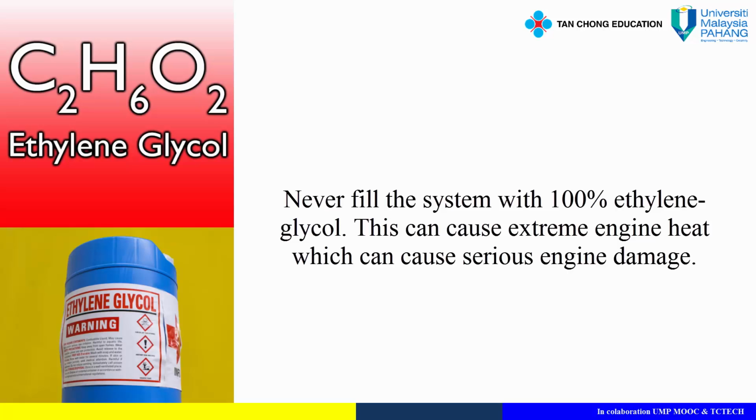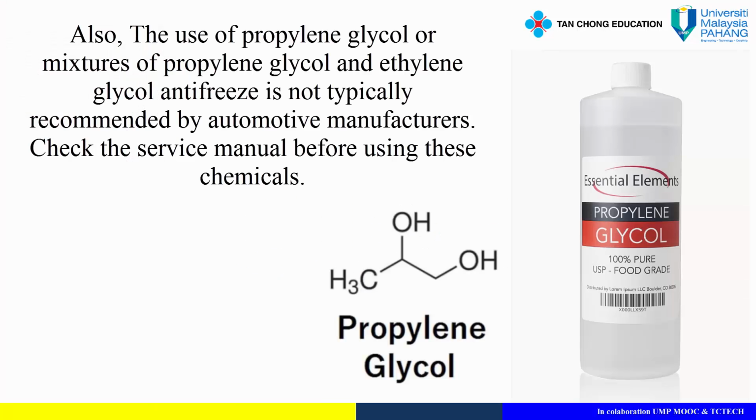This can cause extreme engine heat, which can cause serious engine damage. Also, the use of propylene glycol, or mixtures of propylene glycol and ethylene glycol antifreeze, is not typically recommended by automotive manufacturers. Check the service manual before using these chemicals.